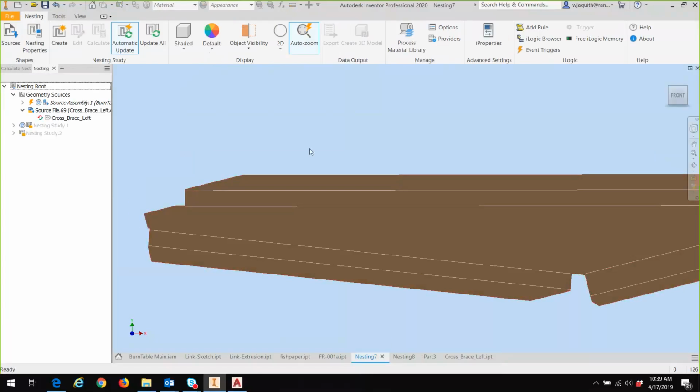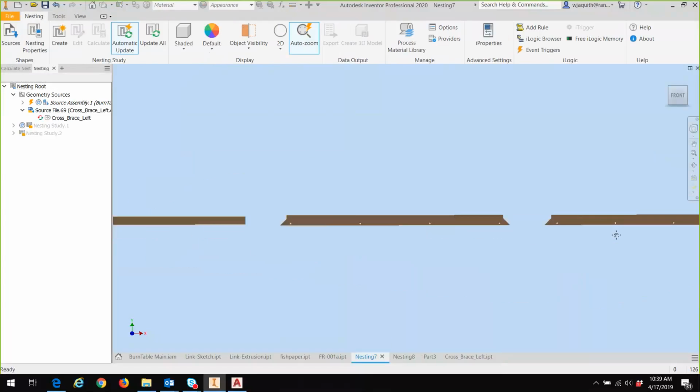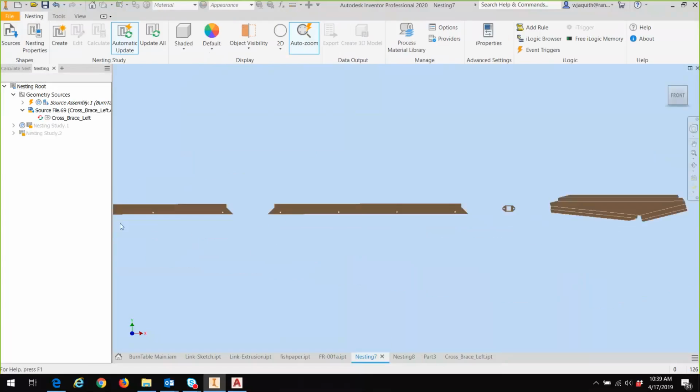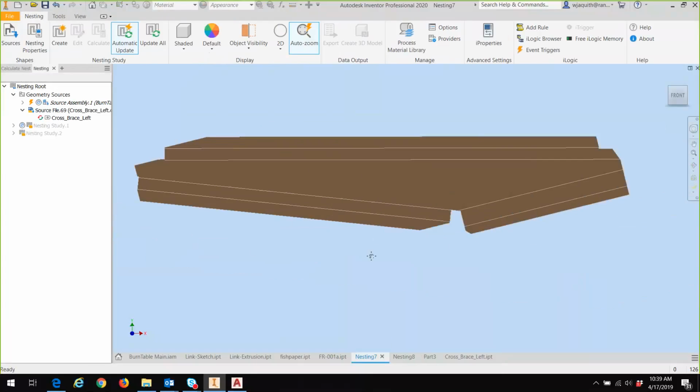This can be useful for etching. This is if you need to do etching or want to etch the bend lines on or some other things like that onto the pattern. Currently, there's no way that I know of to do that with the straight Inventor files. But if I go out to DXF first, I can bring the bend lines in with the DXF. The other thing about the DXF is it will not try to map this.